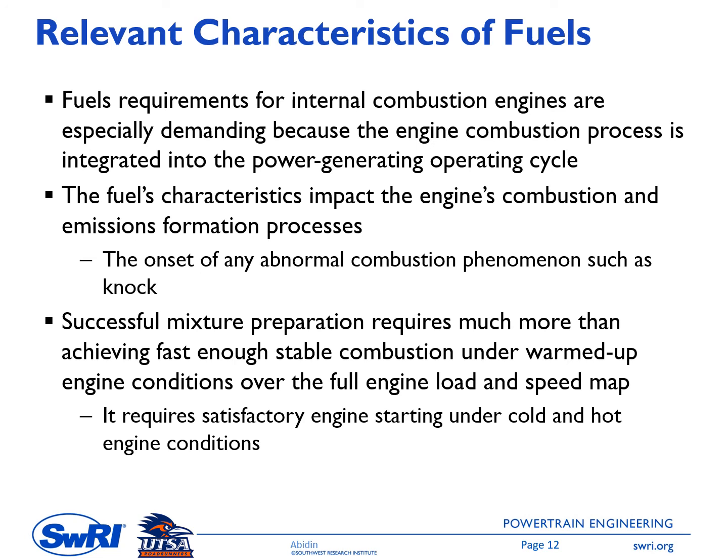Successful mixture preparation requires much more than achieving fast enough, stable combustion under warmed up engine conditions. The reason is we also need to take care of the engine operated under cold and hot conditions. So when we design the engine, we need to make sure that the engine has good performance for cold start condition, for hot start condition, and typically for all available engine operating conditions.